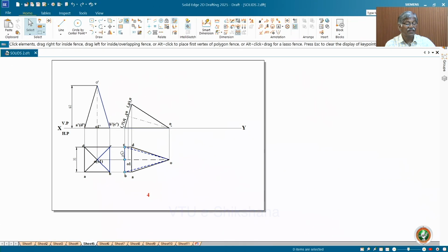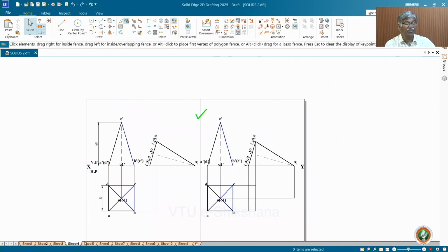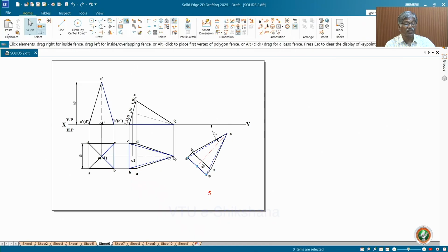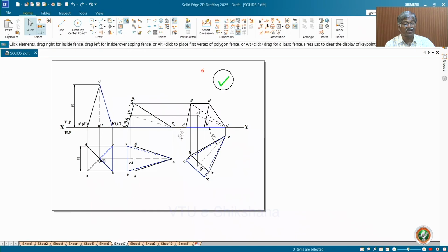Now, here the visibility concept is given. Top face, base is visible, and then completed. Then next comes this one. You have to redraw it such that axis is inclined at beta degree to HP. Base is nearer to the observer, so base is visible. This is right. Now, what possibilities are there of committing mistakes?